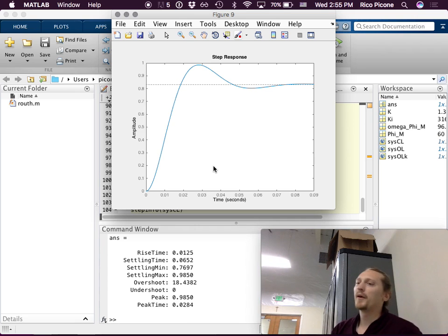When you get to this point, actually, going back and choosing a different phase margin is just more work, because you know this is a monotonic function and the gain is going to decrease if you go one way and increase if you go the other way. So instead of picking out a phase margin to iterate on, you might as well pick out a gain to iterate on, because they're essentially equivalent in this case. So yeah, I would just probably adjust the gain around until you got the overshoot that you wanted.